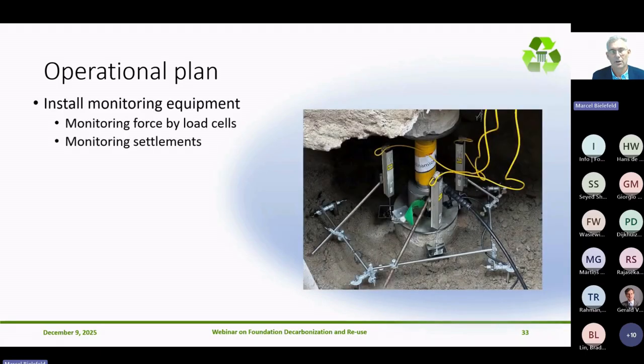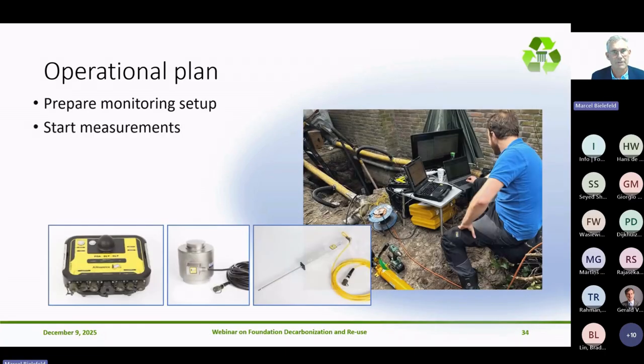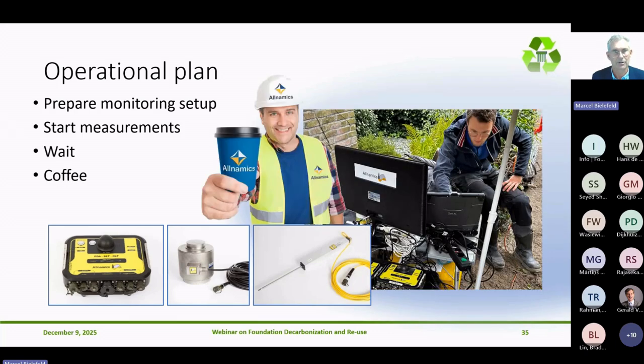And next to the load, the hydraulic jack, we have of course to monitor that load. So additional were calibrated load cells and 2 extensometers to monitor settlements, and a reference frame to monitor the settlements of the pile during loading. And once everything is set up, our engineer can sit out in the sun. Most often it's rain anyway, but can sit in the sun and do the test, not in the pit but just outside. Start the measurements, and as you are aware, a static load test takes a while. So performing a static load test is in general a combination of waiting and drinking coffee.